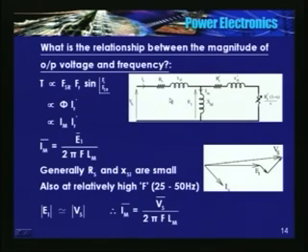Torque is proportional to Fs, Fr, sine of the angle between Fs and Fr, or torque is proportional to FSR and Fs, sine of the angle between FSR and Fs. And the third expression is torque proportional to FSR and Fr, sine of the angle between FSR and Fr.